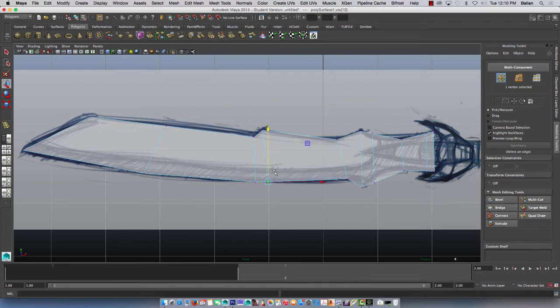Okay, so it's not perfect work right now, and again, you guys can spend time and fix all this, line it up, make it symmetrical, all that business. It's up to you. I can slide this over a touch. You can see here I'm going to need more cuts over here for sure. So here, 1, 2, and I'm going to hold shift. Let's see if this works. I'm going to press R, bring the 2 in like that. You can also use your scale tool. So I'm going to take these 2 here, scale down a bit more.